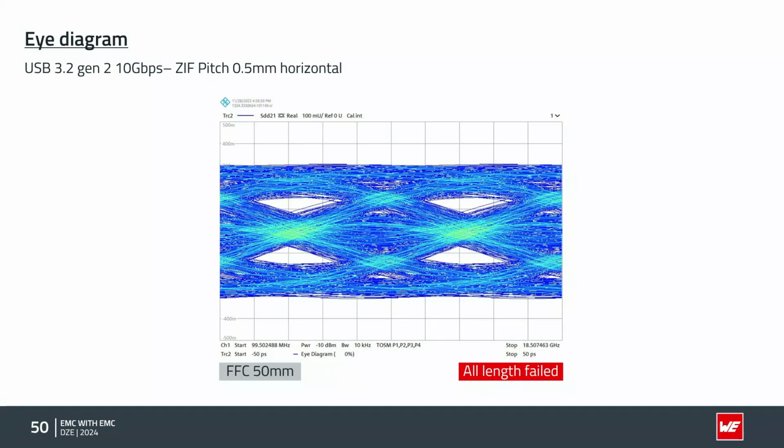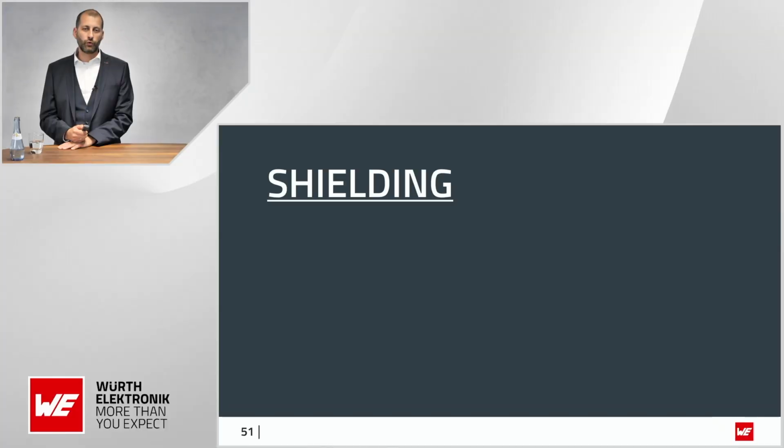Well, simply put, because we can now test all sort of signals. Maybe you want to transmit a certain signal, let's say, I don't know, HDMI over our wire-to-board connectors. Simply put, crimp connectors. Well, we could test it. The only thing we need is the description of the eye diagram, and then we can do the tests in-house. Of course, it's always a bit time depending. My colleague has to do those measurements, but yeah, we will try our best to do that.